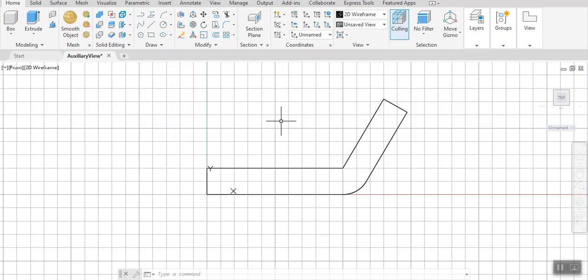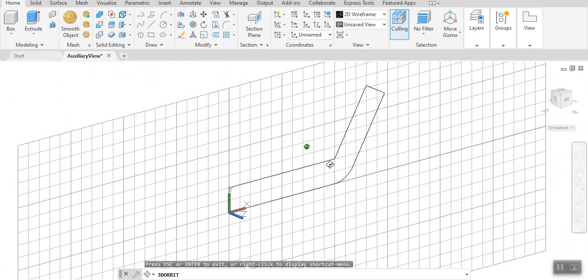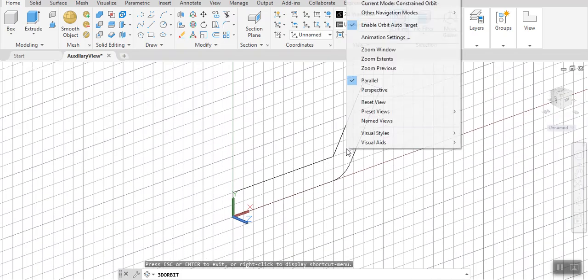This is the indication that all the lines are connected, tied together to become a closed polyline. This is the essential part of AutoCAD extrusion. If you don't do this, AutoCAD will not extrude a solid model. Okay? I just want you to know this part because I was almost forgetting.